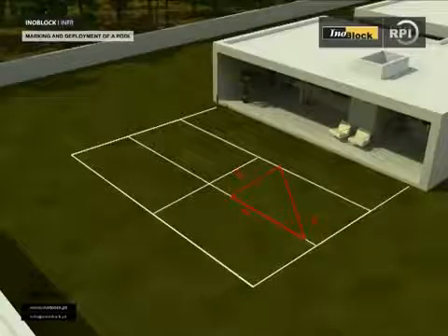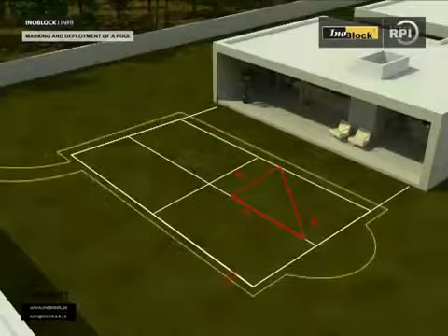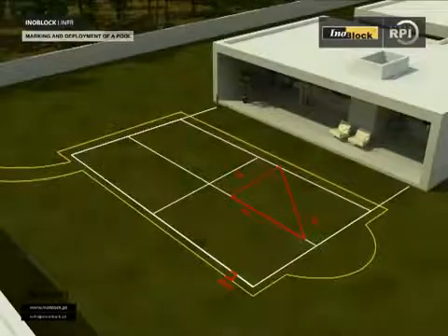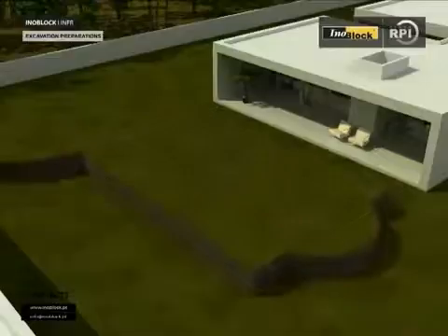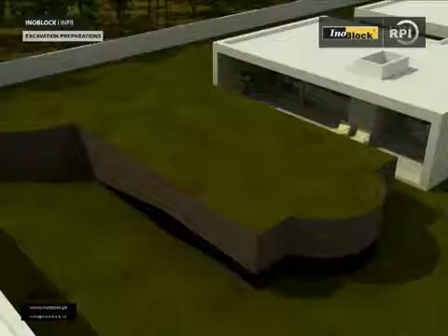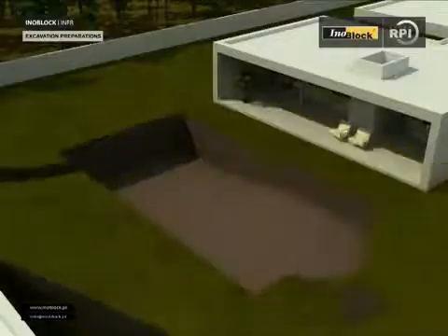The excavation should be at least 60 centimeters on all sides bigger than the finished pool size. This allows for ease of working and for installation of pipework. This can be backfilled later. Remove the excavated material from site. Remember to retain sufficient material for backfilling.